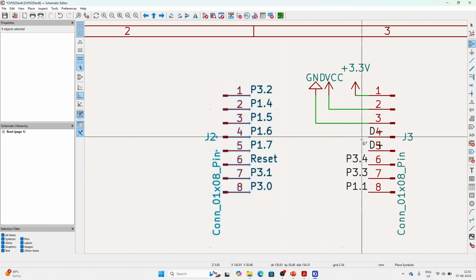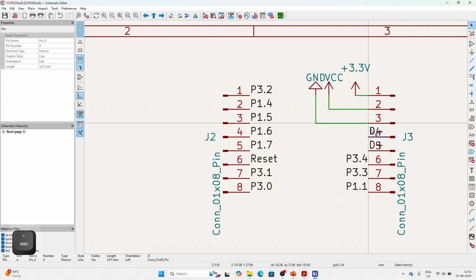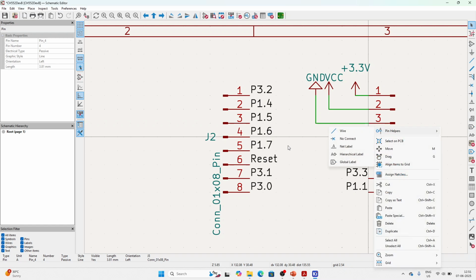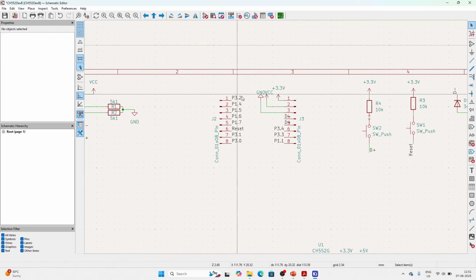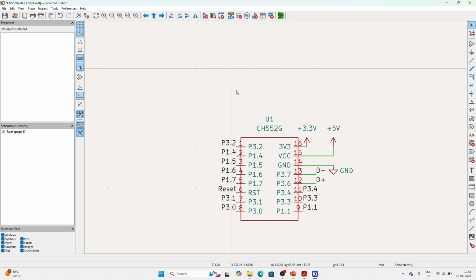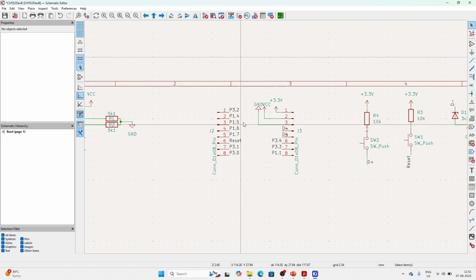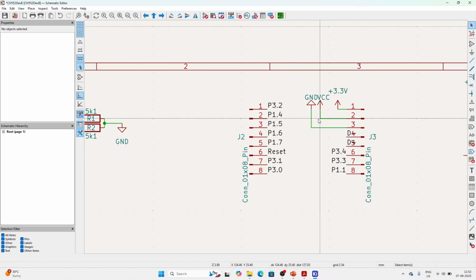The right side also has similar tags, right? Once that is done, this becomes the right and the left side of the headers. So we have the same pin numbers here and the same pin numbers here. I'm utilizing connectors of 2.54 mm width between two legs of the connector, because that's what is friendly with breadboards. So that's what I've done.